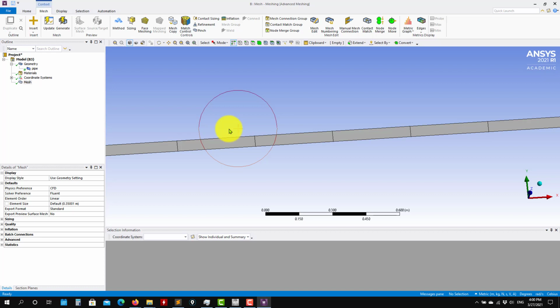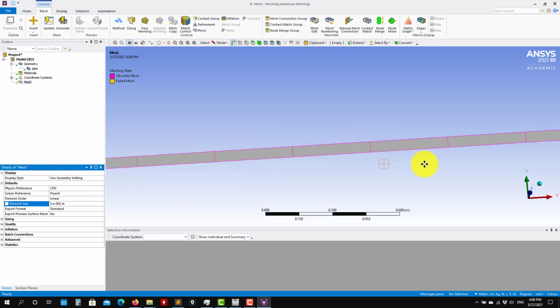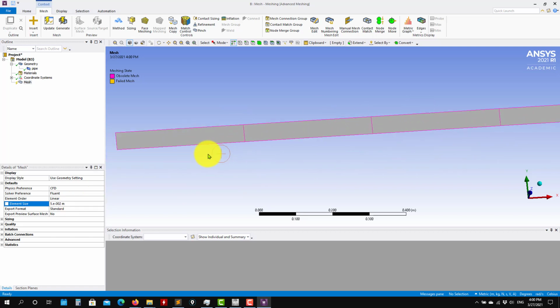And that dimension is a global parameter and can be controlled here. See here that one corresponds to 0.35 meters. So let's put here 0.1 meter, which corresponds to the diameter, and see that you have it there. So the radius is 0.05, the maximum cell. So here you can already start to choose the maximum cell dimension, but remember you have global and local.